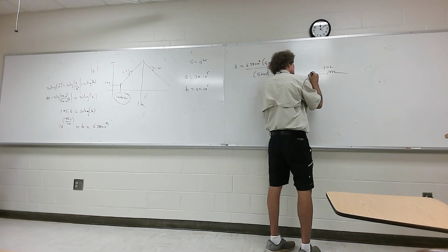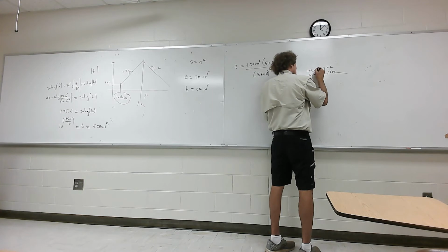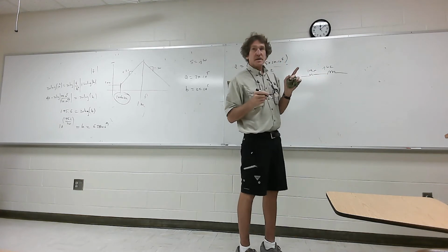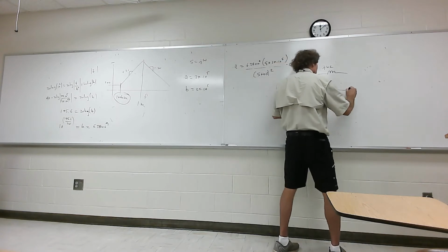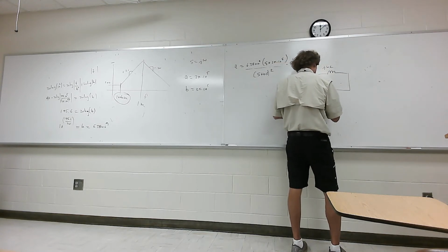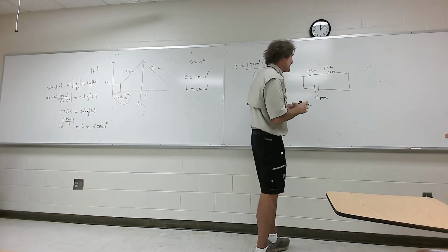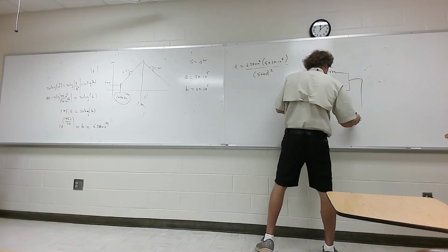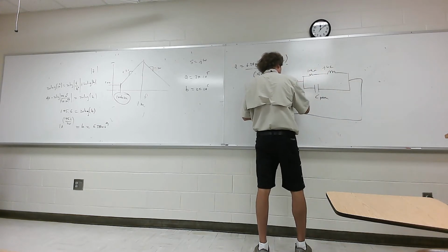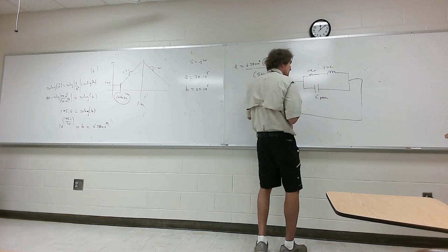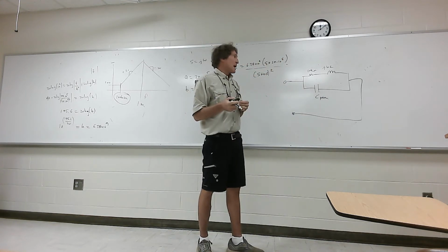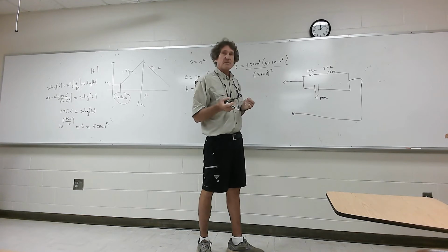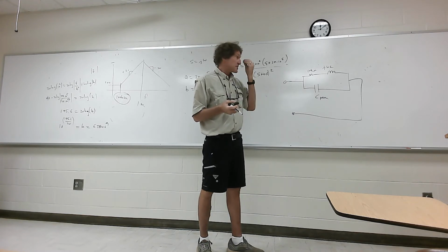In our case, it's 100 ohms. So this is 100 ohms right there. Now, there's also going to be in parallel with that a capacitance, and this is a parasitic capacitance. This is the way the whole circuit looks, if I come over here and here, this would be what the actual circuit element would look like as an impedance model, a model that's typically accepted in the frequency domain.